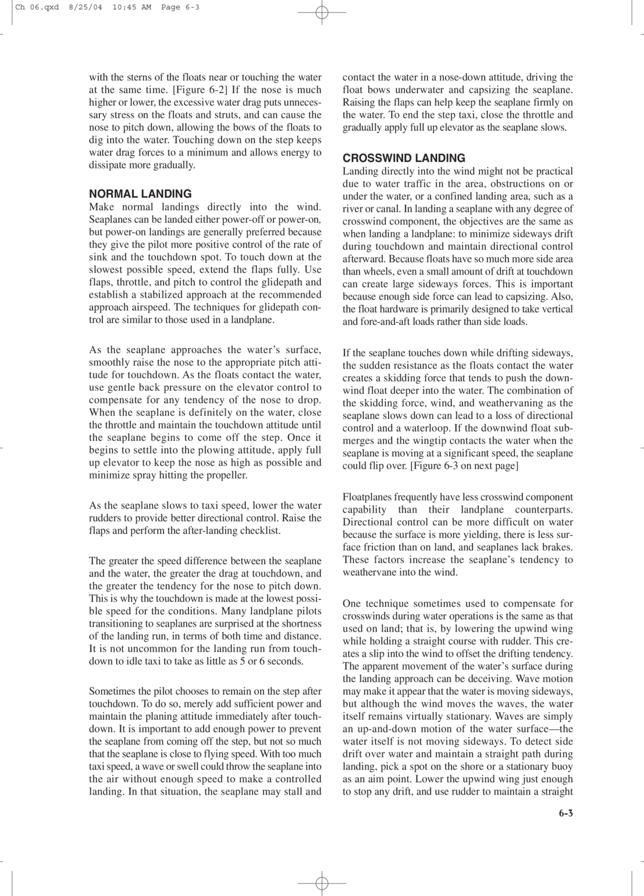The apparent movement of the water's surface during the landing approach can be deceiving. Wave motion may make it appear that the water is moving sideways, but although the wind moves the waves, the water itself remains virtually stationary. Waves are simply an up and down motion of the water surface; the water itself is not moving sideways.